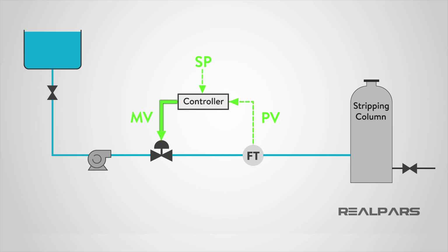I need to design an experiment that will tell me how the process reacts to a change in the valve position. This will give me an idea of how to configure the control equation to most effectively control my process to the given set point.